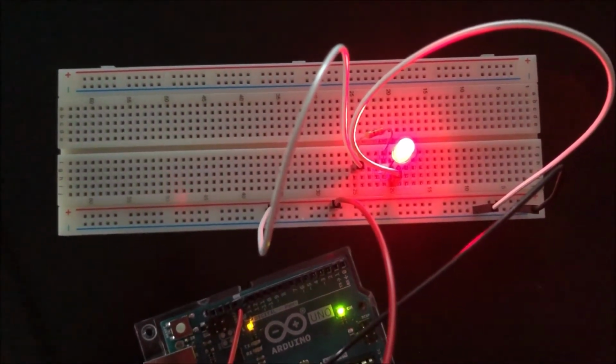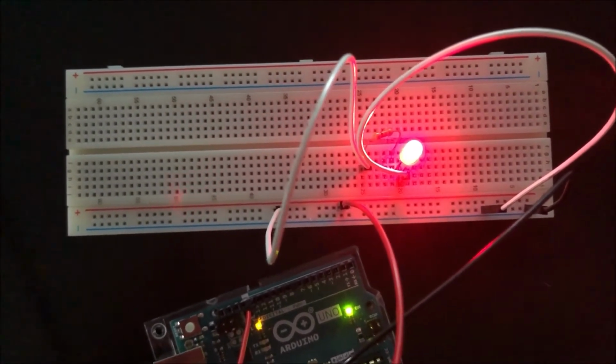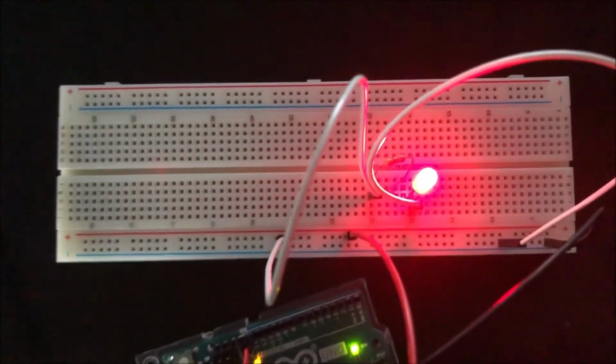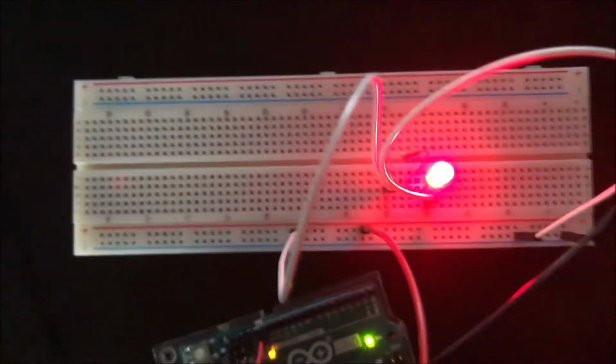And we can now see that it appears, at least from the camera, that the LED is no longer flashing. In actuality, with my own eyes, I can see it flickered. However, when I make the delay length value 10 milliseconds, it registers as always being on through my eyes.